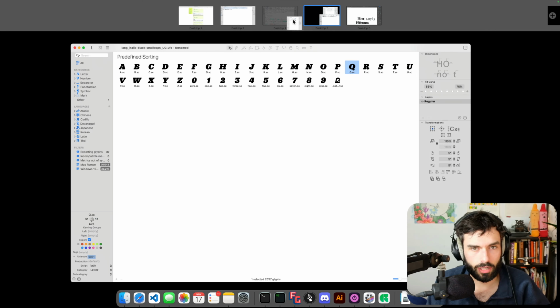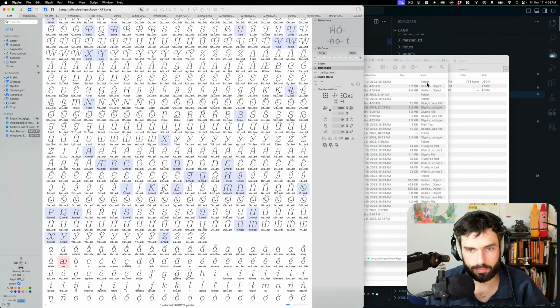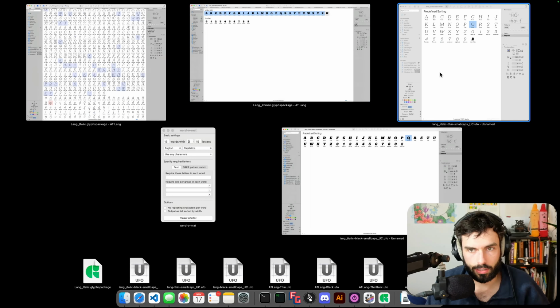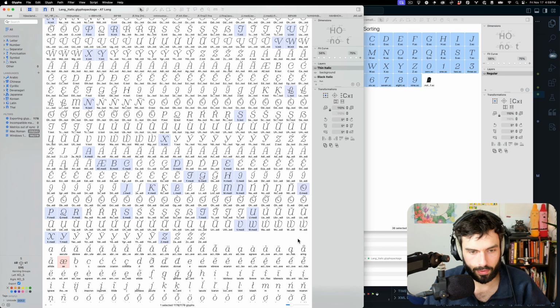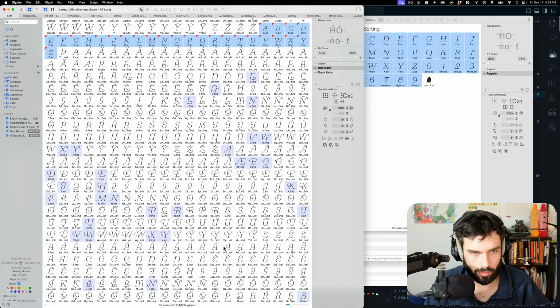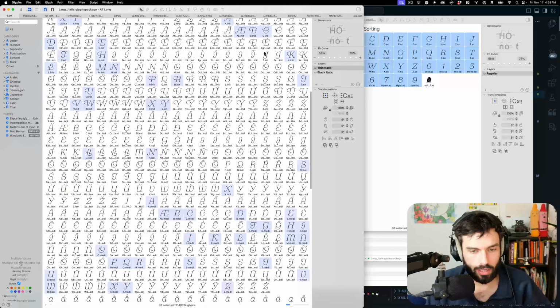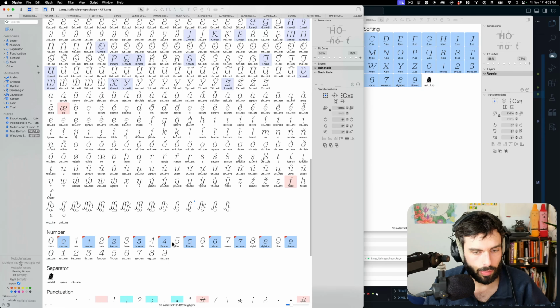The first time you copy and paste new glyphs between documents in Glyphs, it's pretty darn easy. We're just going to copy all of these, Command C, come over here, Command V, and there, it copied it with the names. Pretty solid, but there are a couple of problems.